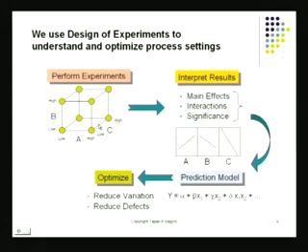So there are 8 different ways in which I can run this process when I'm manipulating these factors A, B, and C. Each can be set at two levels. What I'm really trying to see now is, can I combine 2 and then 2 and then 2? Can I combine them? And that combination is done by this special matrix there. I'm going to tell you a lot more about these matrices. These are called DOE matrices. These are special factor manipulation plans. These are special plans that really enable you to conduct these different experiments by appropriately adjusting the different treatments that this process is subjected to.